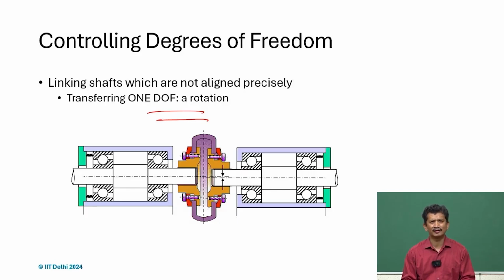And what we realize is that if we are looking at those numbers, the friction and any kind of rolling contact may not be good. So, in that case the coupling has to be proper, and we can use the exact constraint design approach, and then we will see that we can eliminate friction related problems, the virtual backlash, the hysteresis part.